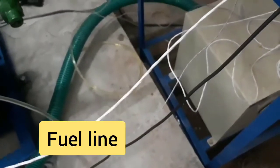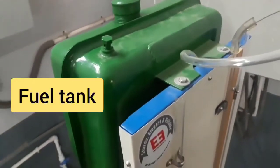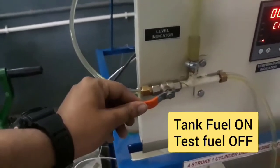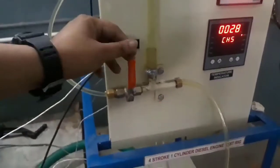This is your air inlet connection with the air box, which supplies the air inside the diesel engine. This is the fuel line, which is connected with your burette. You can see here this is your fuel line, which is coming out from the burette. And this is the fuel tank from which we supply the real fuel to the engine. For test fuel we use the burette, and for the other we use the engine. Here is the fuel on-off valve. When it is off, the fuel is coming from the burette, and when it is on, the fuel is coming from the fuel tank.